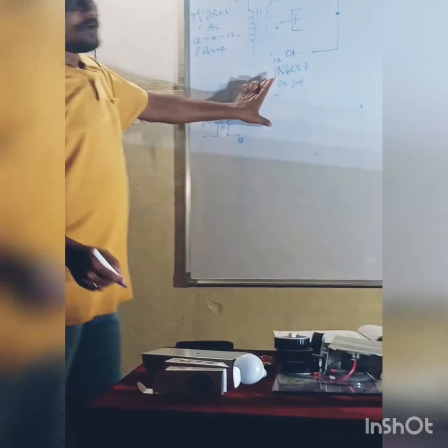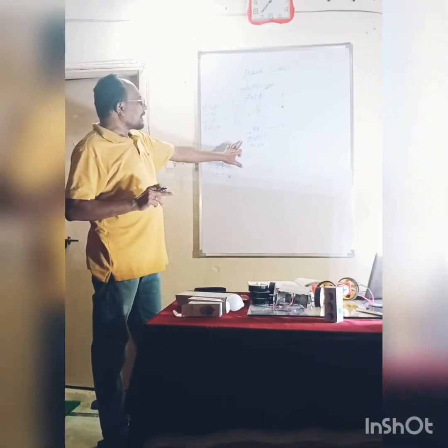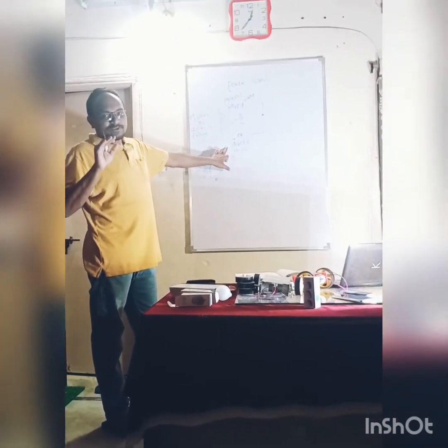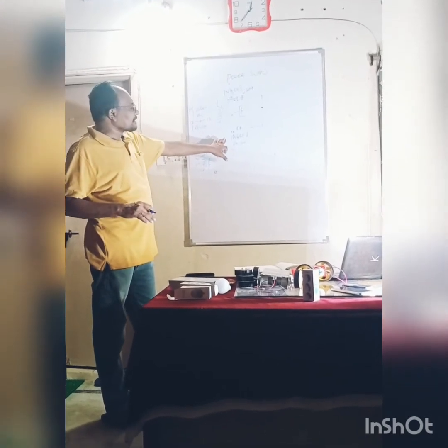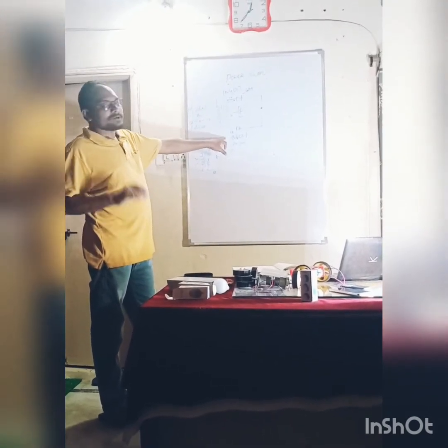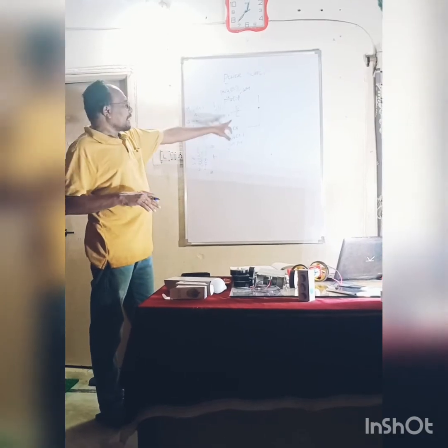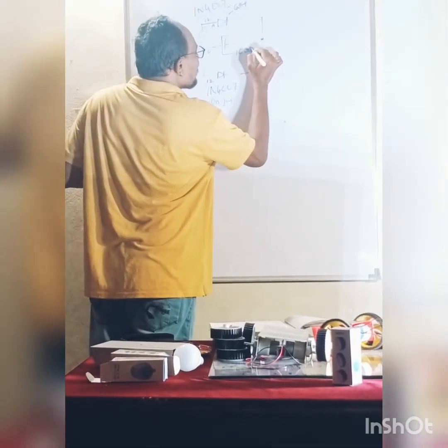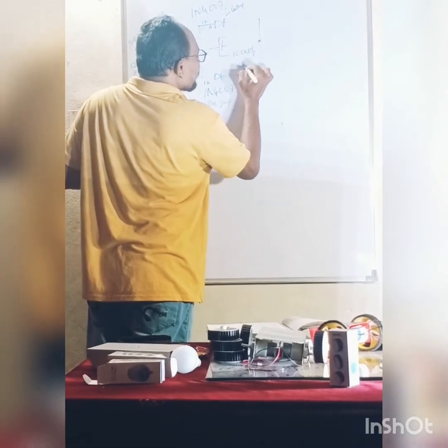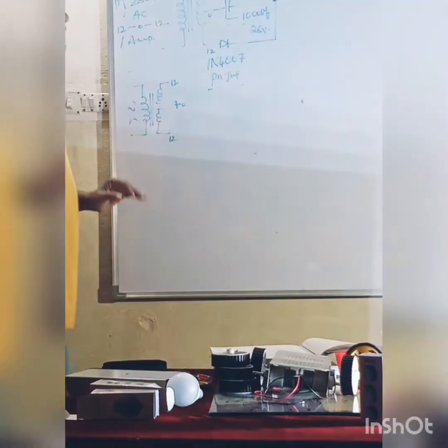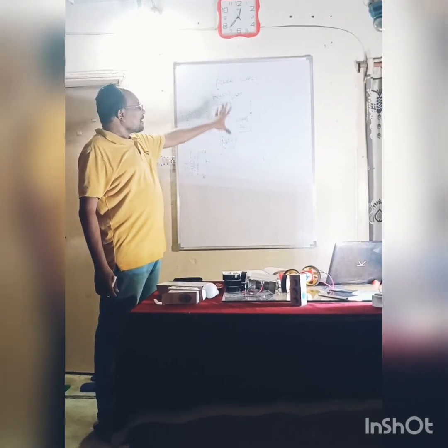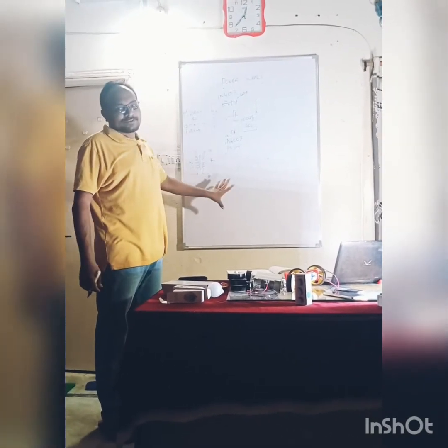Now in Google you have to search data about these diodes, why I selected 1N4007, and also collect some theory about PN junction diodes. The filter capacitor value will be 1000 microfarads, 25 volts. Now your assignment is to tell me how I selected these values.